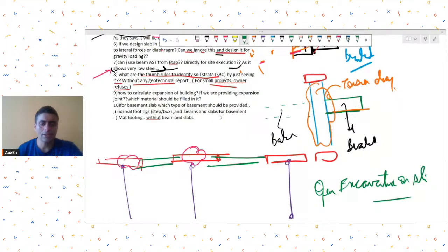If you start getting, let's say, yellow or murum type of soil, then around 18 to 19, 20 tons per square meter is a good approximation. If you start getting hard strata, which is difficult to even break by the arm of your excavation equipment like JCB trucks, then around 25, 26 tons per square meter is the approximate SBC you can get.